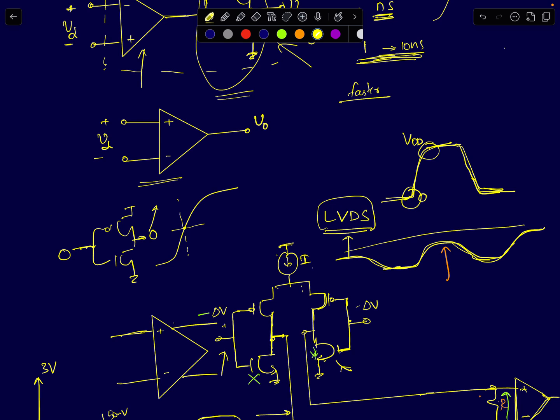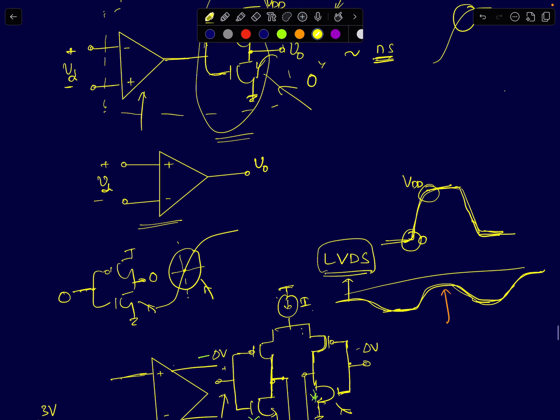Okay, so when it is charging, the NMOS or PMOS transistors go through different regions of operation. Usually when it is closer to the mid rail, your transistors will be in saturation region. If you recall, and I'm reiterating this point because we analyzed this previously for TTL logic as well, for a fixed VGS, a MOSFET will carry maximum current when its VDS is higher, that is, in the saturation region. It will carry lower currents in the linear region, because VGS is fixed. For a fixed VGS, as I decrease my VDS, it will carry lower currents.